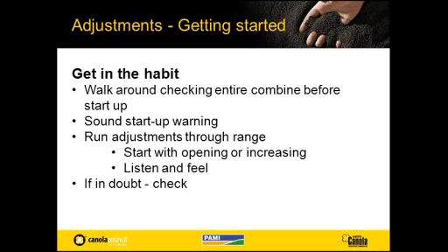Then it's a good habit to run adjustments through their range on a daily basis when you start up. This is to make sure that they have lubrication, and whenever you start, you should always move towards the open. So if you're going to readjust the concave, drop it first, in case there's something in there or jammed up.